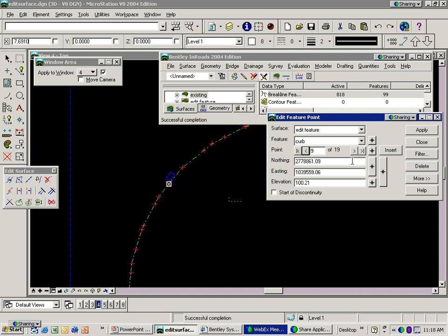The other thing, this tool is very powerful in many regards. We could actually insert a point. And when you insert a point, if I'm here, it will insert a point halfway between the next point. So I'm just going to hit insert, and it's actually right here. It basically takes the slope between these 2 points, interpolates where this is going to be, and adds a vertice. This vertice later could be modified with these commands, and so on.